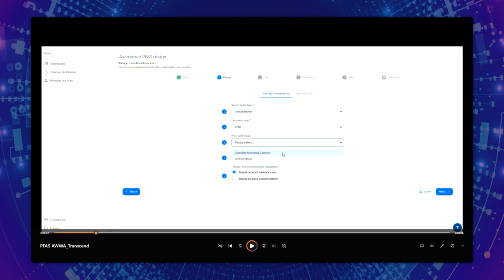At this point, we do have ready both granular activated carbon as an option and ion exchange as an option. So in this situation, you could run one scenario with granular activated carbon, and then rerun another scenario with the same inputs on the ion exchange, allowing you to compare the two. We'll get to that later. And having that opportunity to see which one will be more cost effective or more effective overall by having those two technologies in there. Unfortunately, we still don't have the membranes, but that's not necessarily a drawback. That's why we also have Nick in here.